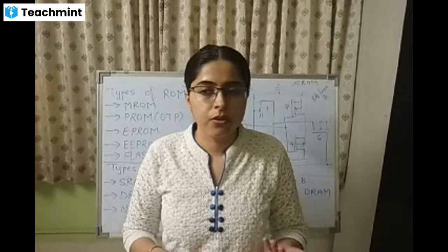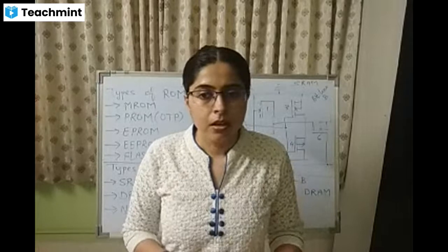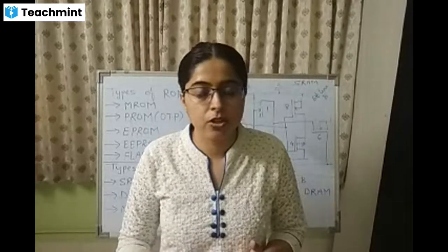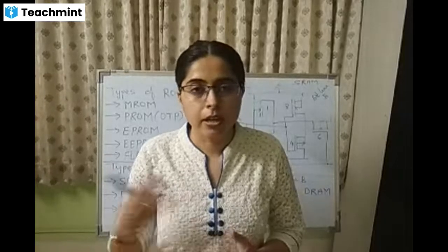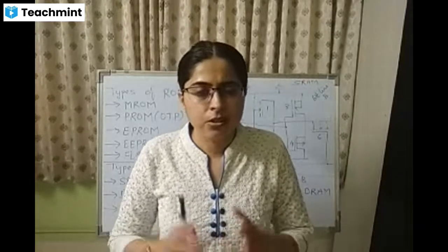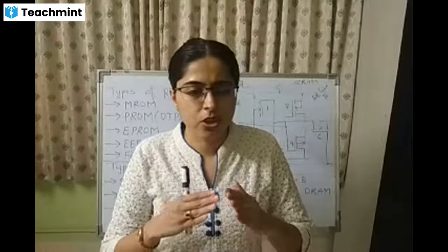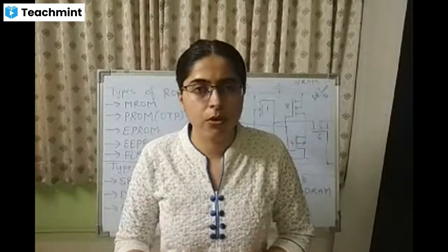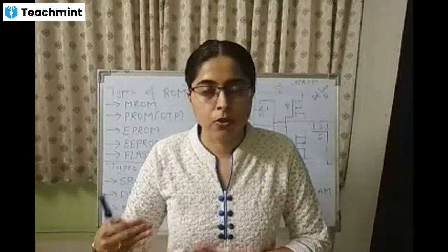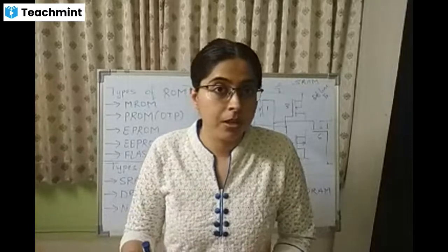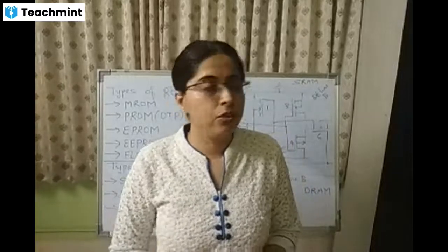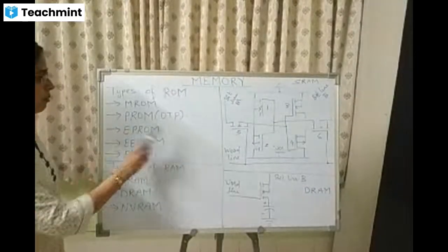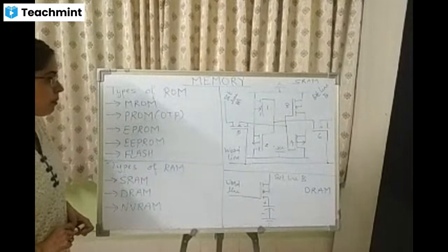But whenever we design any system, its code is subjected to a lot of change. There is a possibility that the code may change. There are modifications in the code, and there are firmware upgrades. So it is not economical. Sometimes it becomes essential to reprogram the chip. Suppose there is some error in the code, or it needs to get modified, or software needs to get updated. We need to do reprogramming, right? So in that case, it is not economical to use this PROM or OTP. So we are using EEPROM, erasable programmable read-only memory.